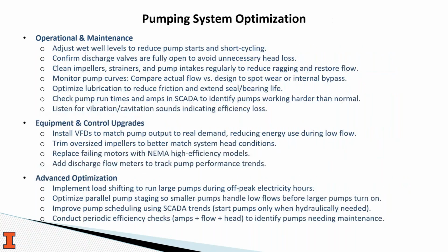On the pumping side, similarly, starting with O&M, what are some of the low cost, no cost upgrades wastewater utilities can do? A simple strategy is to just adjust the wet well levels to reduce pump start time and short cycling, which can extend a pump's life. It's also important to ensure discharge valves are completely open.